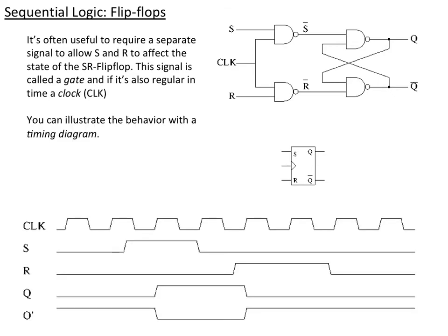That's the same clock as you have on your tester boards in the lab. So we can see what happens. Here's the clock pulse. You see it's very regular. When the clock is high and S is high, then Q will go positive on the next up clock part. In particular, I have a clock here where the transition only happens when the clock is going high, and so it turns on. Here's my reset. I've turned off S, and it only works when the clock is going high again. So we see what happens.